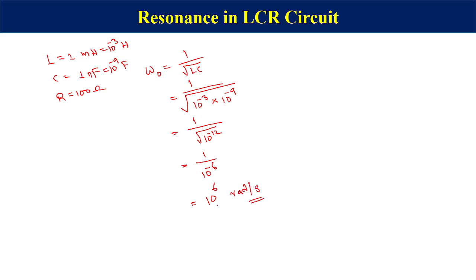So this is the frequency which we have to hunt. So if you vary now the omega from some 0 megahertz to say 10 megahertz, then exactly at 1 megahertz, which is equal to 10 to the power 6, the resonant frequency will be there. So at this particular frequency, current will shoot up to the maximum. All right. Now, why is this condition actually required?